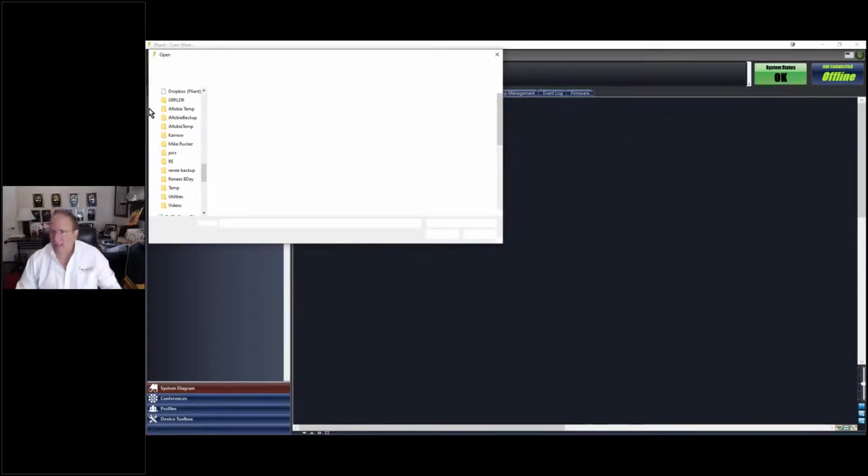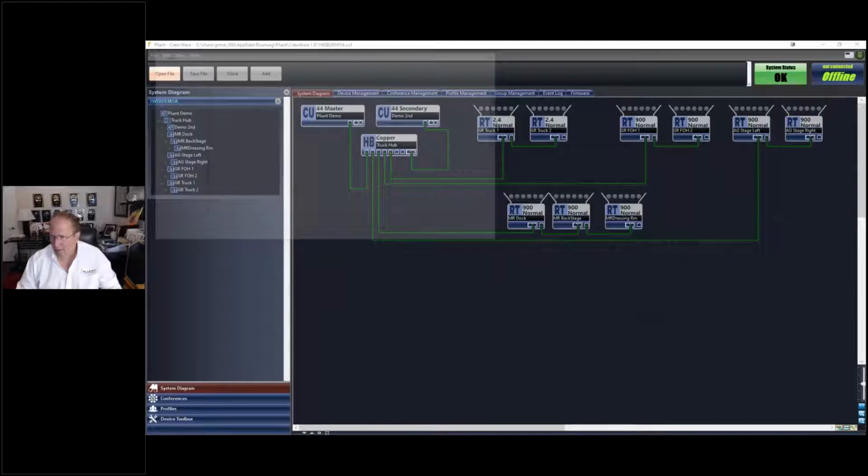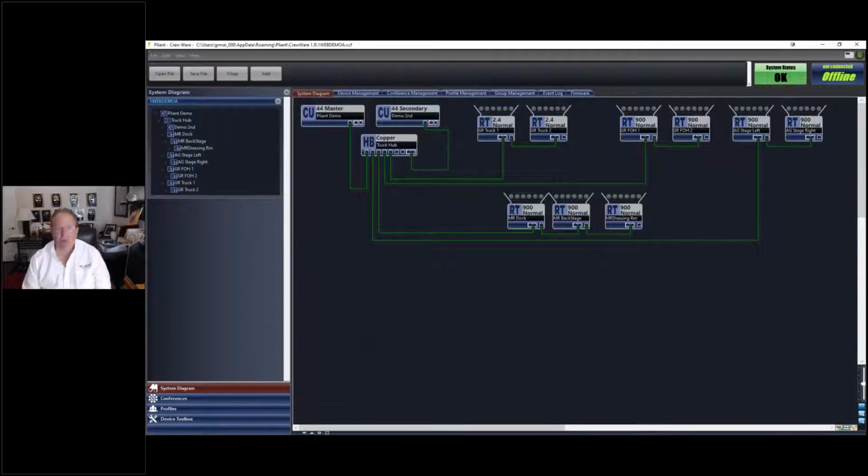This file is called the CCF file, and .ccf stands for CrewCom configuration file. And this represents all of the settings for a system. It's all of the users, all of the devices, all of your settings are in one specific file, and it's very transportable, very easy to use. And once you build up this configuration, you can load it, you can email it to somebody, you can load it into a control unit either directly online or through the USB front port.